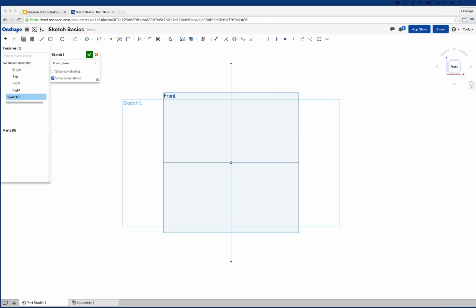You can add as many as you want from start to end, but you can't add a new start and end of the spline. Forgive me if that doesn't answer the question, but again, you can't add it on start and end, just any point in between the two. Okay? You really control the start and end by the two endpoints and those handles.